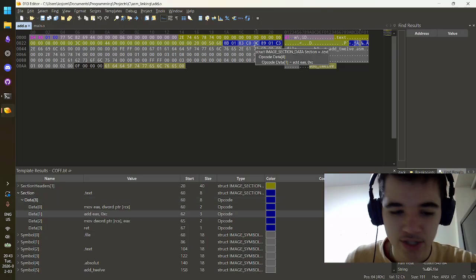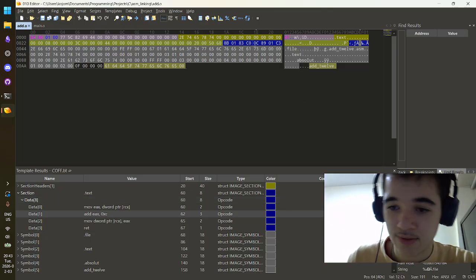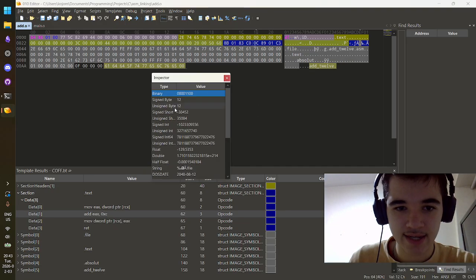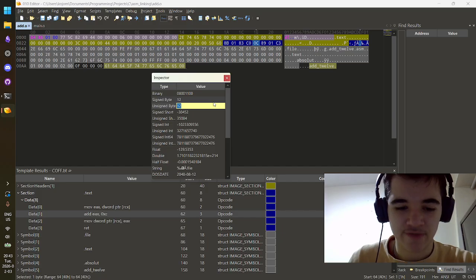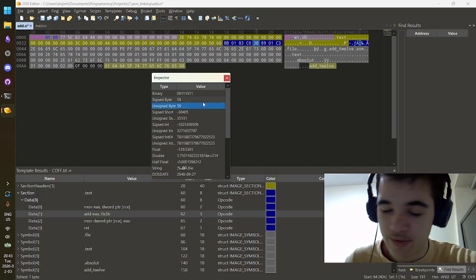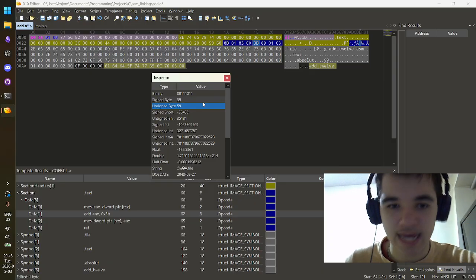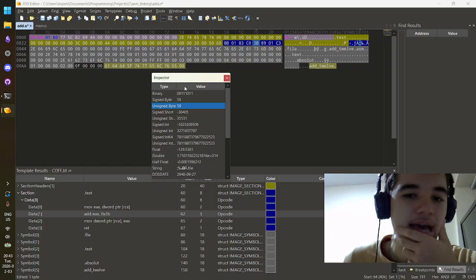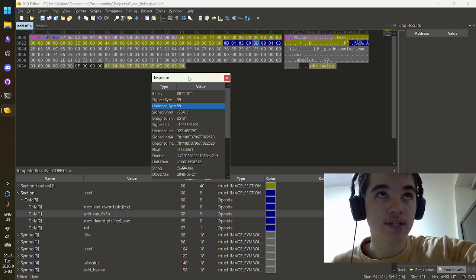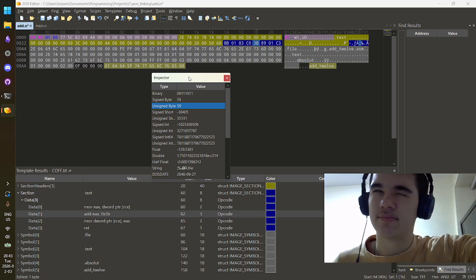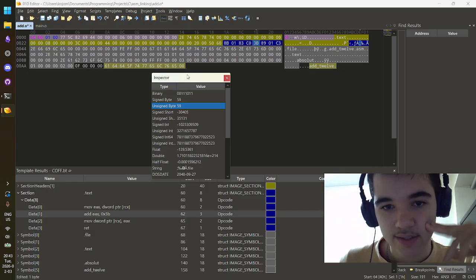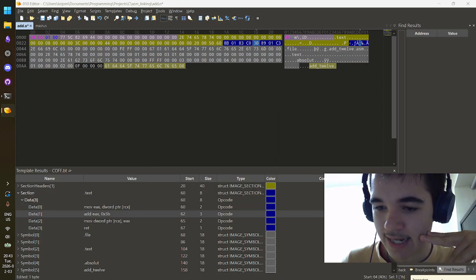Now, I could literally write this out as hexadecimal, or you can just use the inspector, which I'm covering, but it is down here. And we can just go ahead and modify this to 59. And because 59 is well within the range of an 8-bit signed integer for positive numbers, that should be okay. Because I have actually tried this with values greater than 128, I think is the limit, and it goes negative. So for whatever reason, there's something here that says it's unsigned.